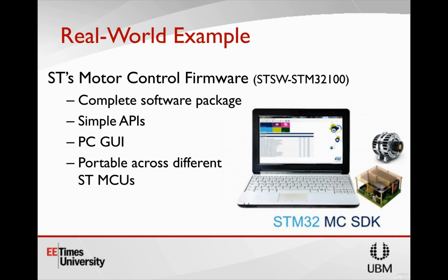It's a great question. I don't really know if there is much of a future beyond field-oriented control. Where I see the key things coming is more advancements in sensorless techniques and in some of the different control modes we talked about during this presentation. For example, more advancements in high-frequency injection techniques that allow you to do initial position detection of the rotor, so you can bypass some of the problems you see with sensorless startup. And even improving the sensorless algorithm so it can work at lower speeds than about 10%.